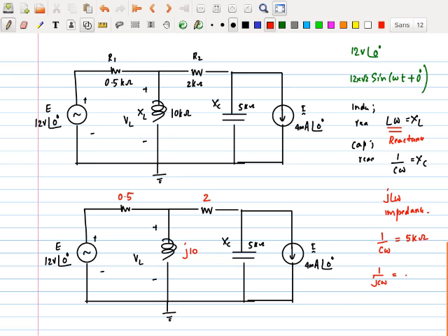But this is also equal to what? It's minus j over C omega. We showed you this last time. Right? Because if I take j to the power 2, it is minus 1. Because j is the root of minus 1, that you used to call i. Right? So, if I substitute this, what would this become? It's minus j times 5. This is already in AC form.